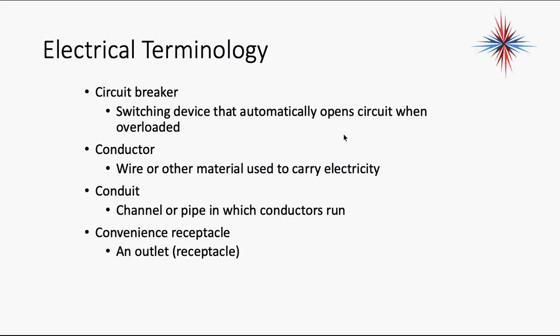It appears that somebody put a new air conditioning system on the roof like 4 years prior, and the breaker panel was not sized properly for that equipment. So for 4 years, they had a chair sitting in front of their breaker panel blowing air across the panel. That's just an example of why we need to make sure our breaker panels and our breakers are the correct size.